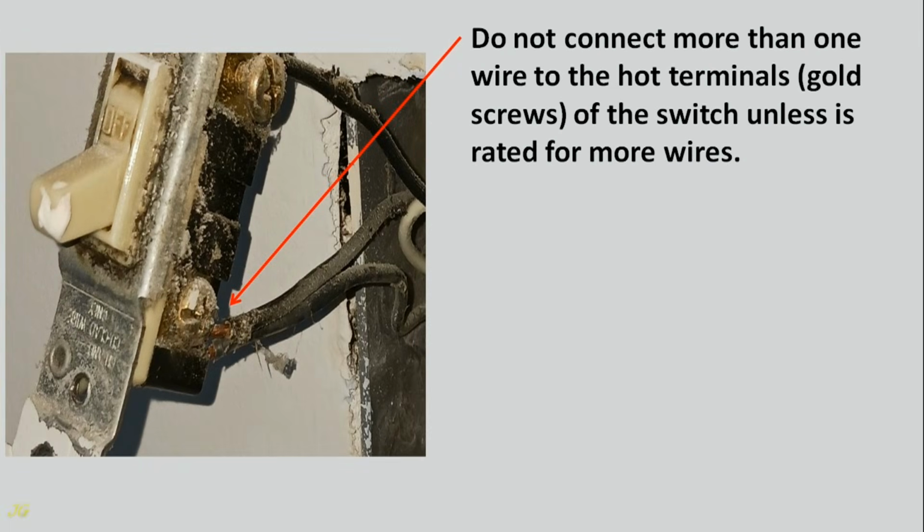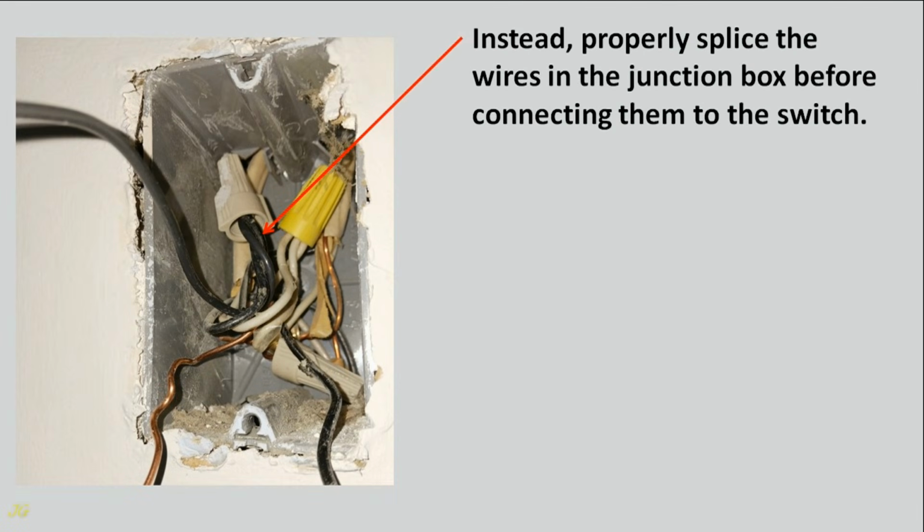Do not connect more than one wire to the hot terminals, gold screws, of the switch unless it is rated for more wires. Instead, properly splice the wires in the junction box before connecting them to the switch.